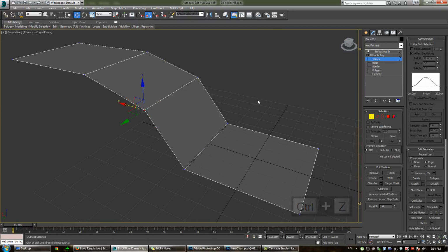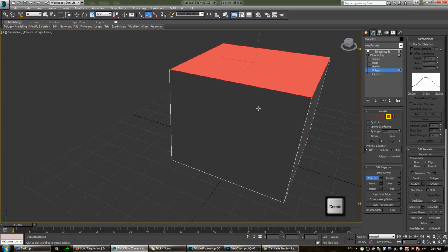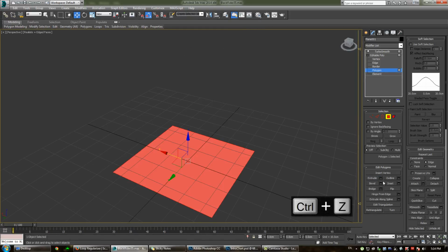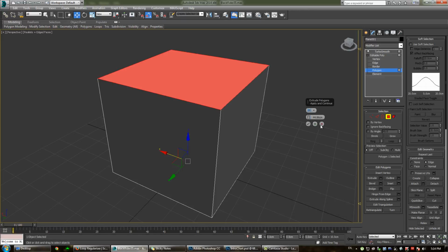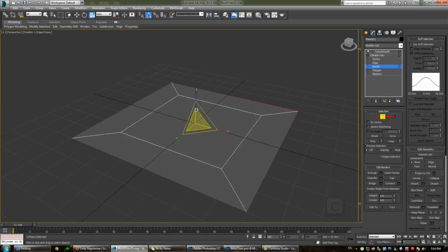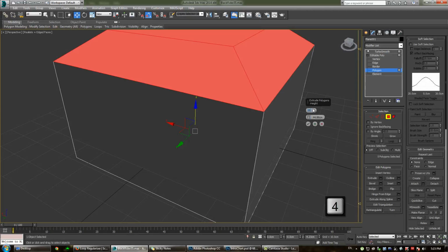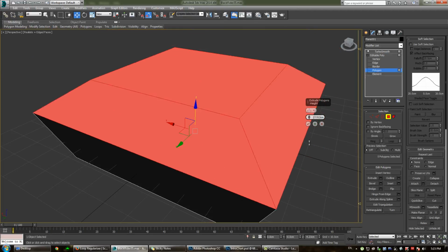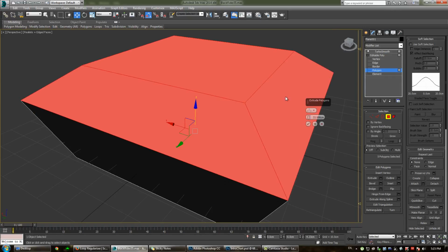And lastly, we've got the polygon sub-object tools used. So firstly, you can use the extrude tool. Once again, that's got an option box as well. And you can extrude by the normal. So what I'll do, just to demonstrate that, is drag out and select all these polygons. Now when I extrude, if I go by normal, it's going to push them out along the axis in which the normal of this face is coming out at.